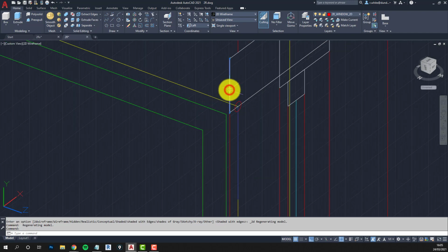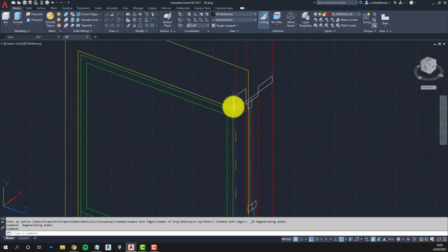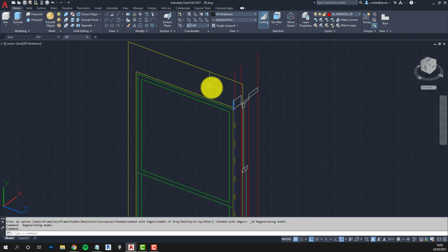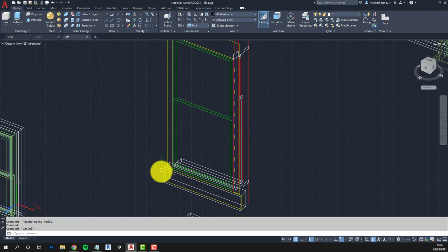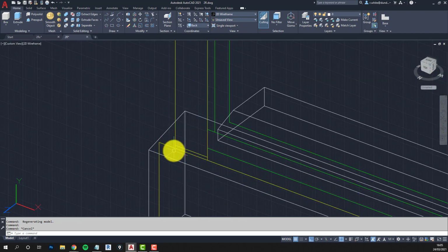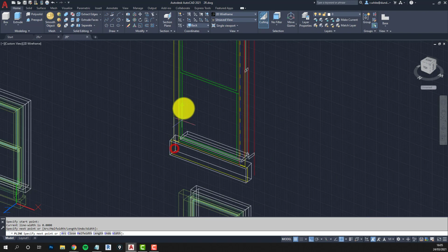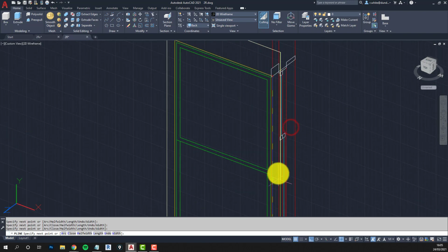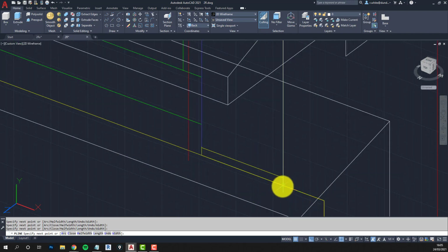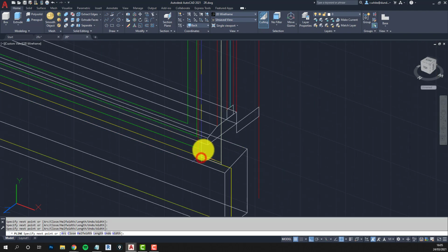Okay, now the shape of this here isn't really going to be much help. It'd be better to model this from the front and extrude it forwards and backwards. So I'm going to change to the back UCS because I'm actually working on the back of the building here. Okay, and then using my 2D information that I've got, draw things absolutely as accurately as you can. It makes making the 3D stuff much easier.